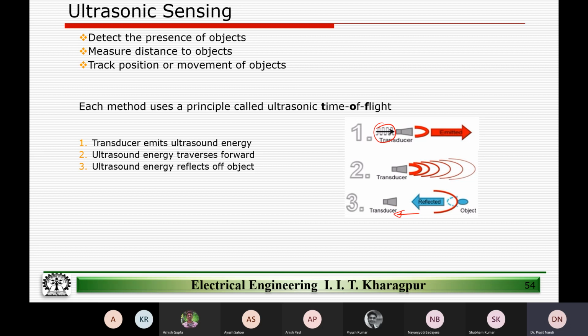It has this reversible way of working. If we apply an electric pulse, it gives us a mechanical deformation, or conversely, if there is a mechanical deformation, that can create an electric field across the transducer, right? That we have studied over the last 10, 12 classes. So that same basic utility of the piezoelectric material comes into the picture here.